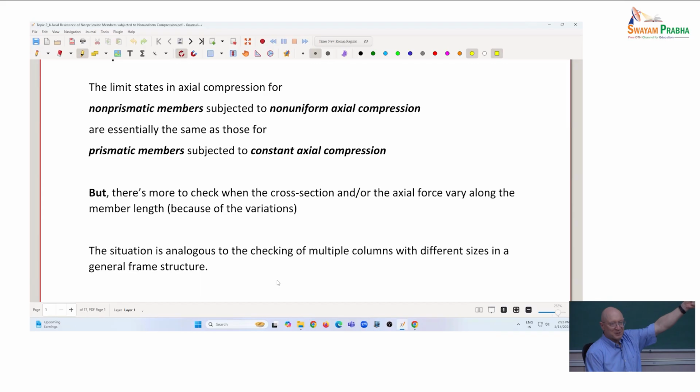I've got my elastic PE in each column, or my elastic FE, the stress. Then you would take that to the column curve, be it the Indian standard or the American standard or any other standard, and you get a factored axial compressive strength of each column.